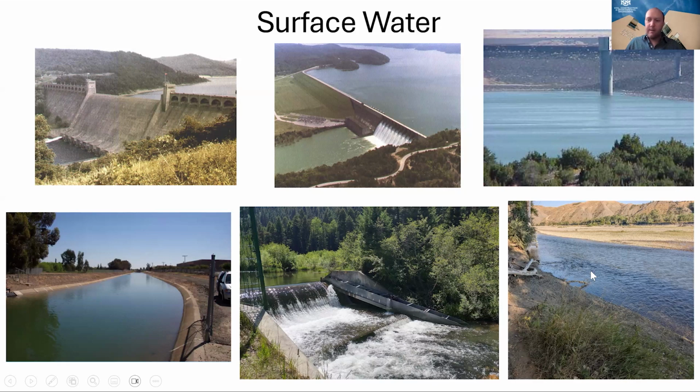And so these are all in a bit of one category of how you take that water in, because it can be taken directly from that surface. We'll talk about in a minute rivers that are lower and don't have as good of an intake structure, so what is utilized is called an infiltration gallery. We'll talk about that in a bit.